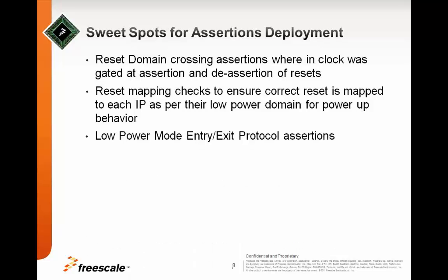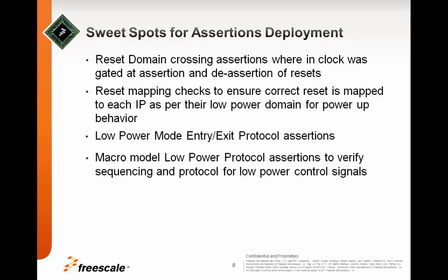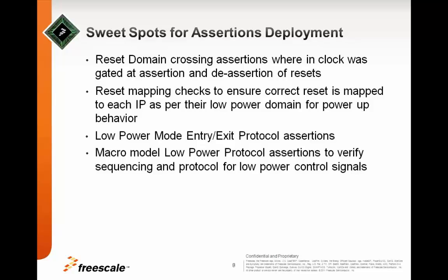Then we also have the low power mode entry and exit protocol, and macro model low power protocol assertions to verify the sequencing and protocol for low power control signals. In our SoC design, we have macro models like Flash, which have critical low power control signals mapped to the always on domain, such as the Flash low power enable signals as well as the acknowledgement signals.